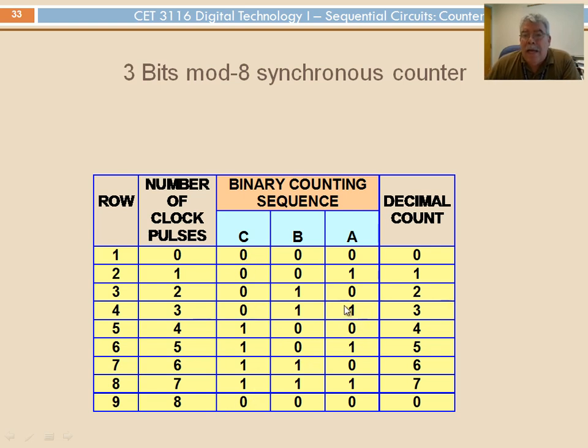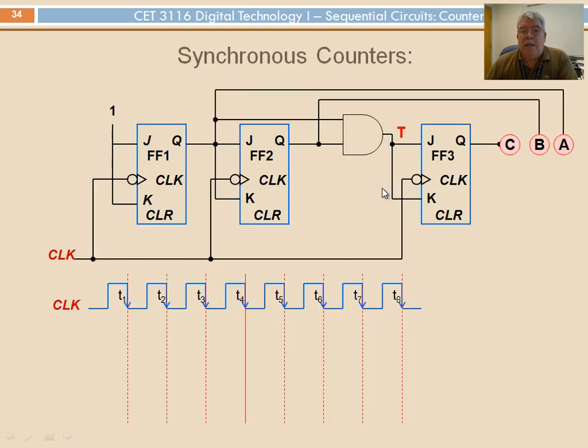So see that I need to force the most significant bit, in this case C. It will change only on the transition from the 4th to the 5th row. And then we need to force that when? Well, what I could do is see exactly what are the values of A and B for which this value needs to change, or do a toggle, between this 4th state and this one. How do we do that? Well, very clever. This is the way we do it.